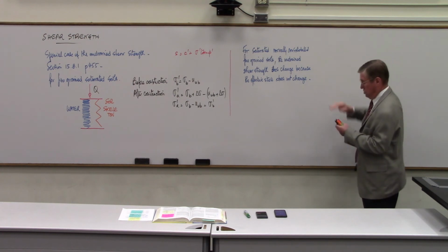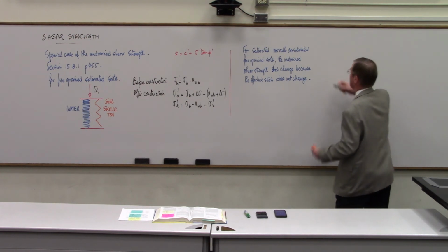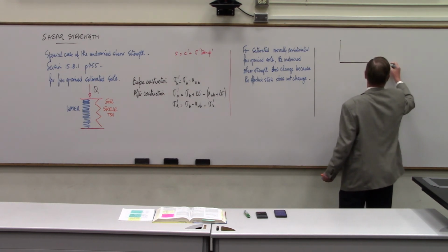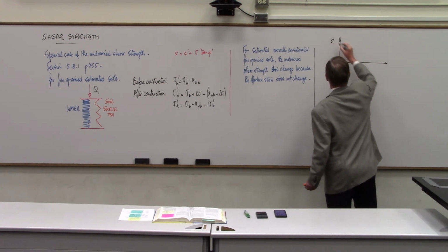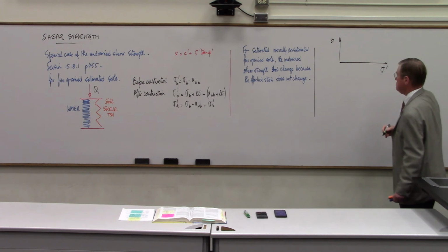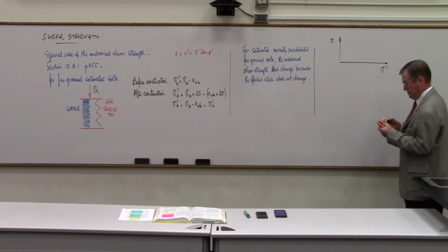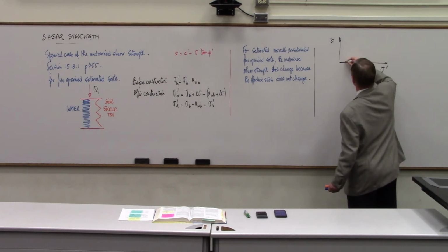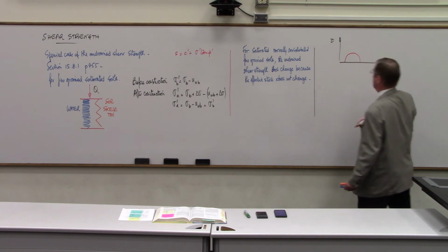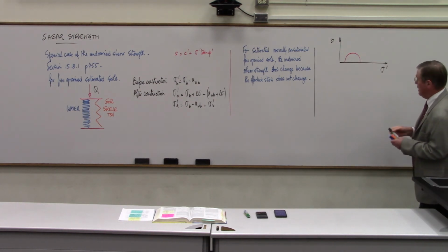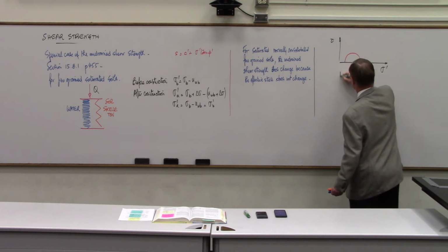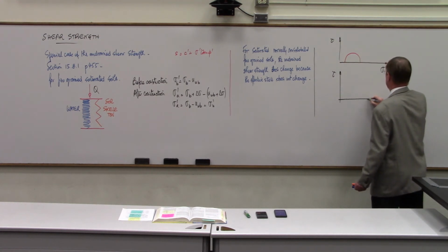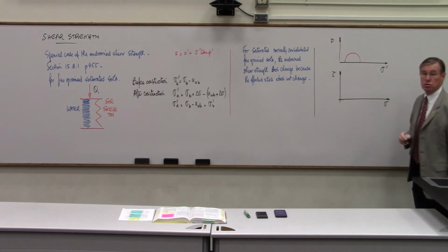So in essence, and I'll do the diagram right here, in essence what happens is that if you have the Mohr-Coulomb set of axes, shear stress, effective stress, and on this set of axes you have a Mohr circle that looks like this, and then you run a first test and you plot something that you shouldn't plot, in my opinion, and you happen to plot it versus the total stress.